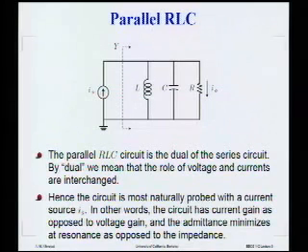Yeah, it's just the inverse. So just like Z is a transfer function that, if you know the current, tells you what the voltage is, right? Y is the opposite. So if you know the voltage, you can find the current. In other words, I have a source current here, and I want to know what the voltage is on this parallel RLC circuit. Okay? Other questions?